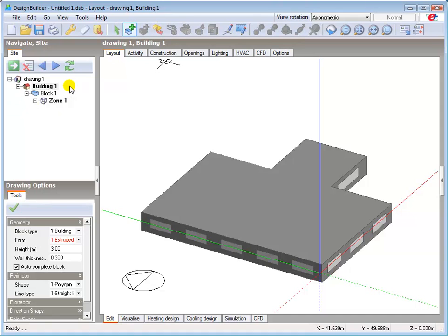We'll now add a second block to create the first floor using the same drawing options. Moving the cursor around the first block, you will notice that each surface changes colour as the crosshair cursor is moved onto it. Also notice that the orientation of the crosshair cursor changes to match the plane. When we're drawing in 3D, we must take care to create the geometry in the correct plane, and the changing surface colours and cursor orientation help us with this.